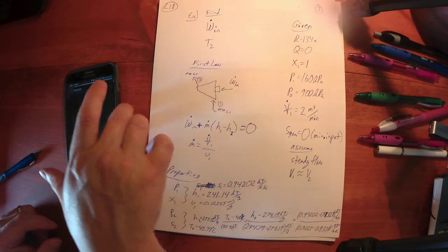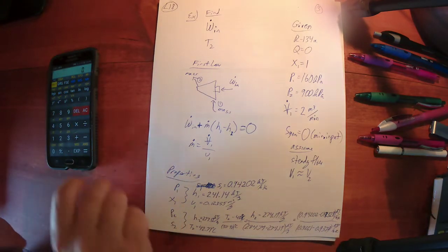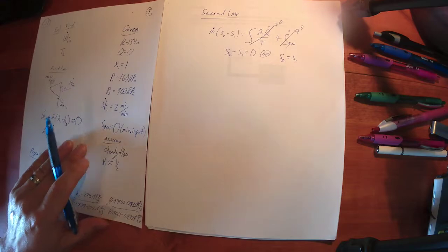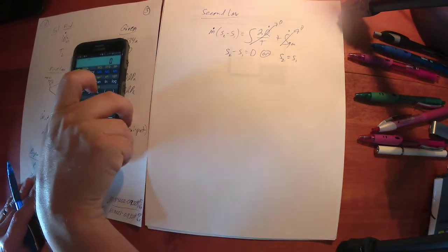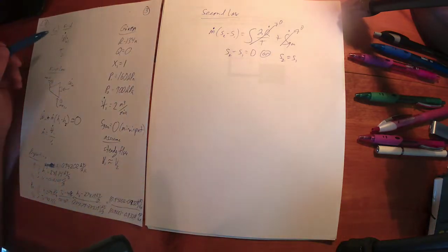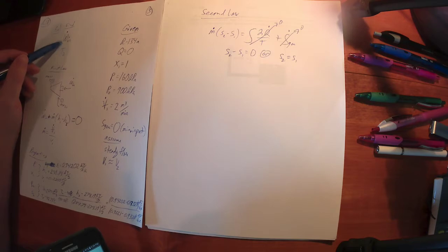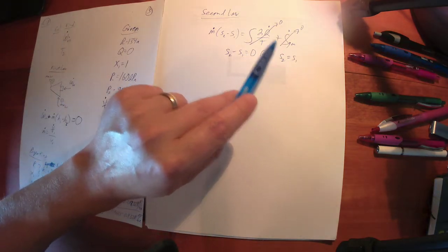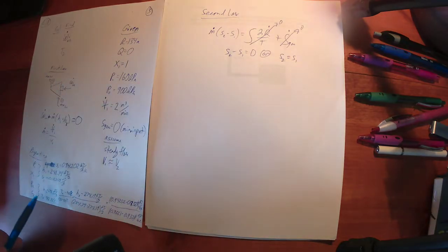Okay, now, all right, we're done, right? That's what we got to do. No, we're not done. This is an engineering problem. It's multiple steps. It's complex, and there's a lot of algebra and units involved, and that's okay. That's just how it is. What are we looking for? We're looking for the power input, the minimum power input. So we're going to find power where entropy generated is 0. That comes out of the second law, which tells us the entropy is constant because it's adiabatic and reversible.